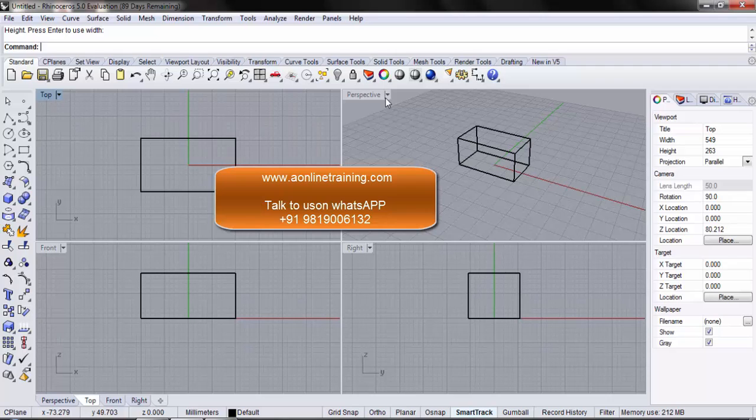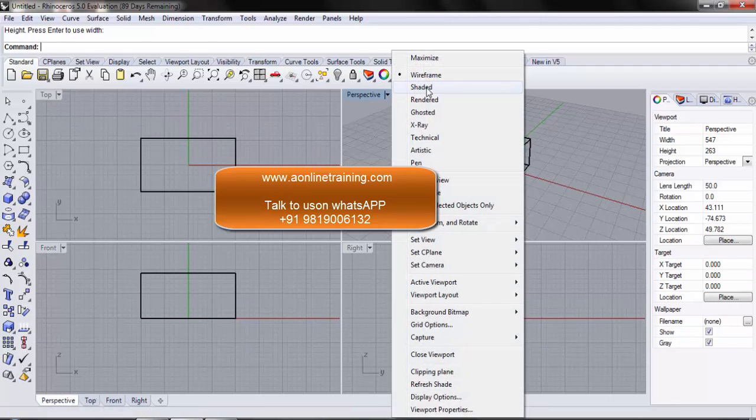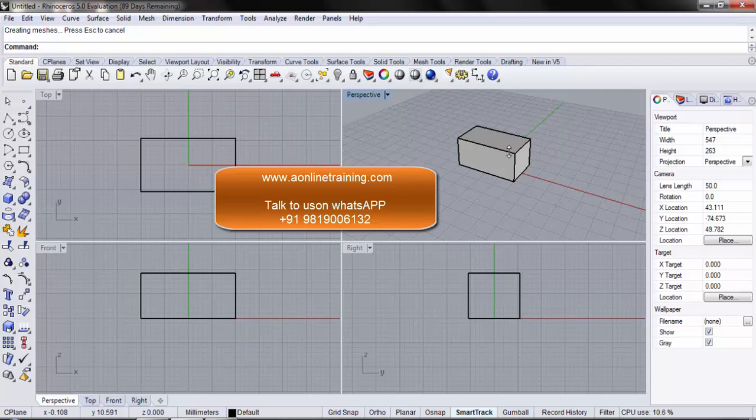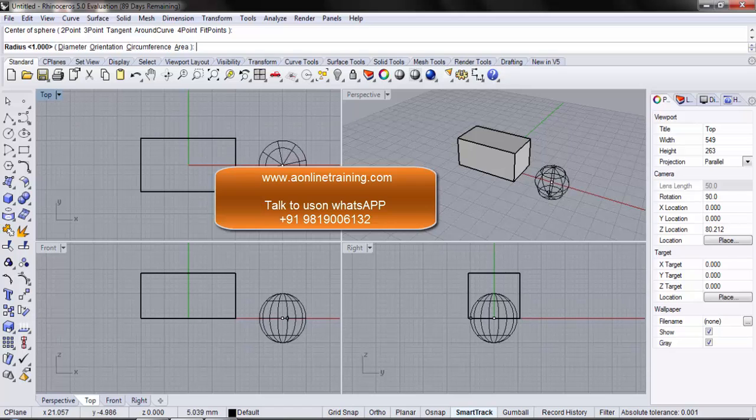Now next I want to explain you about layers. So under perspective view, I will go back into shaded so that I can see the shade color over here. Now I will create a sphere. So under the box you have this icon, keep it pressed. I simply come to sphere. I click on sphere. Now I do not want it to start from 0. So let's say I can move my mouse over here on the right hand side. I click and I create the sphere.